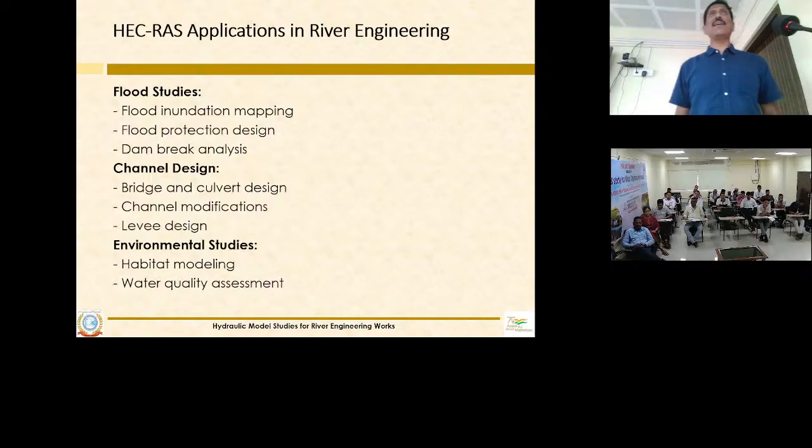Then bridge and culvert designs. These are standard requirements for bridges: what waterway you are designing, whether it is sufficient, what afflux it will create, and the orientation of the bridge. All these aspects can be studied in the HEC-RAS model.